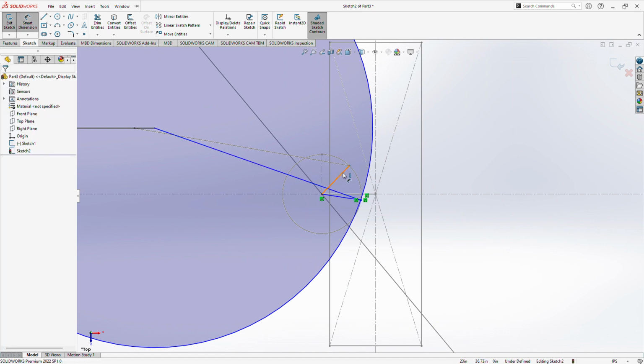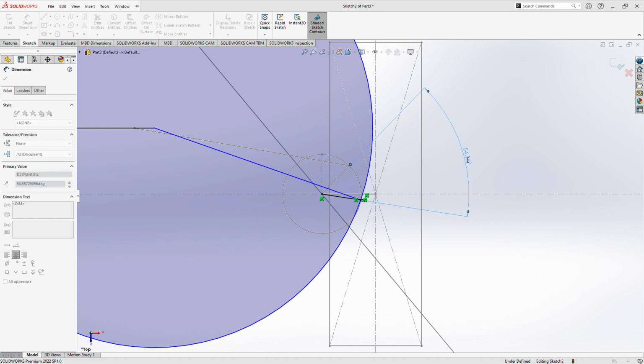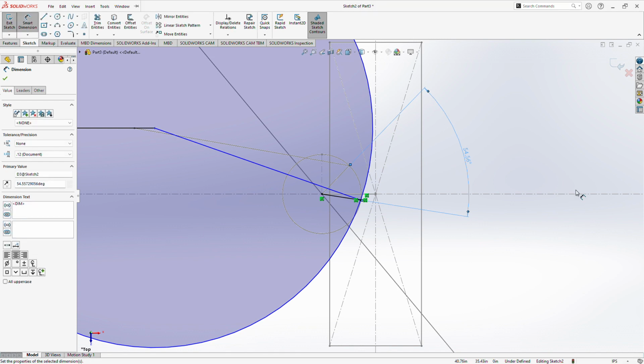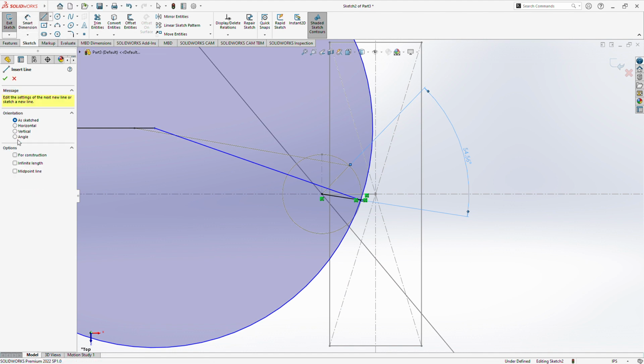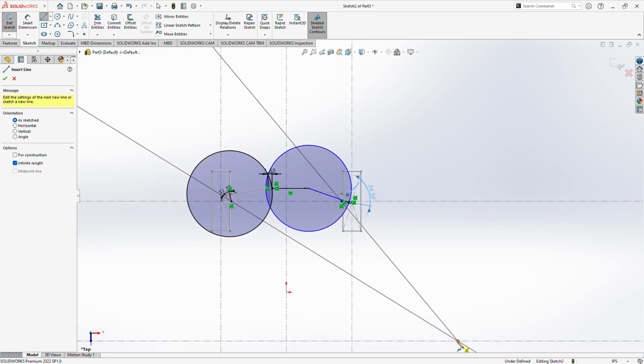Measure this angle here. This is 54.56 degrees. Okay, this is the actual turning angle when the vehicle is taking a right turn. Okay, the geometry here is completed. Let's see where this line intersects a line where we assume the vehicle is taking a 100% Ackermann turn.